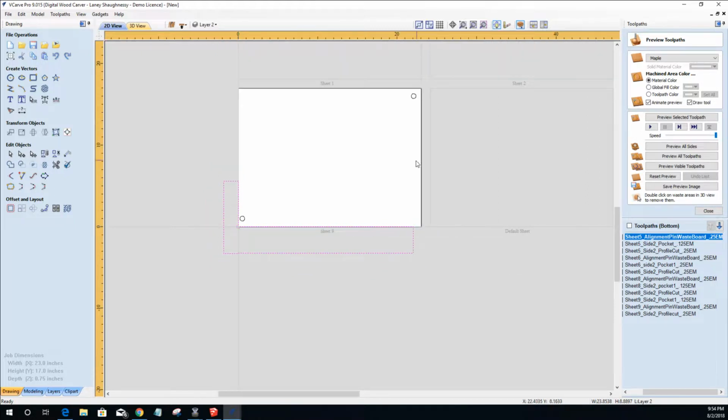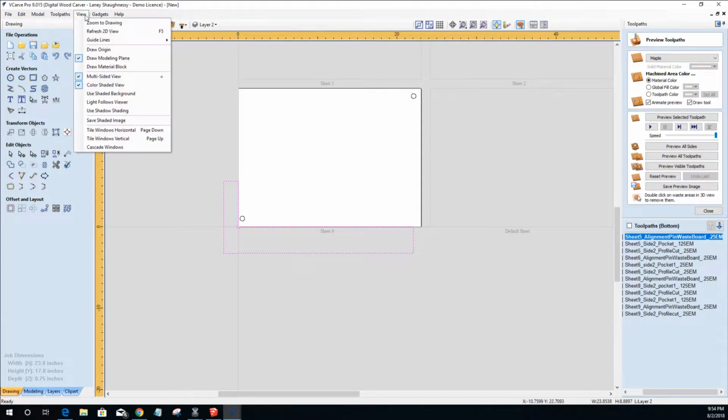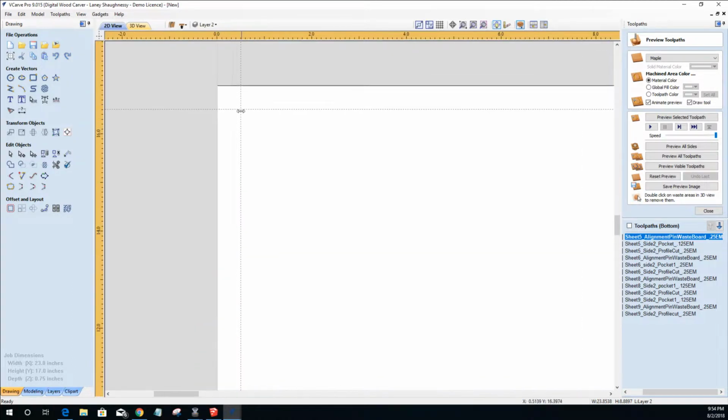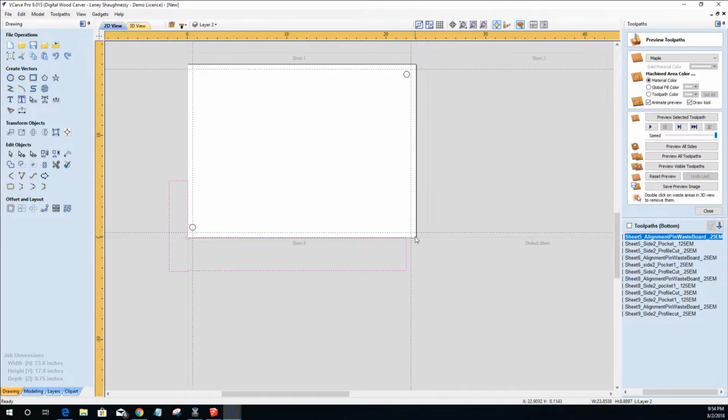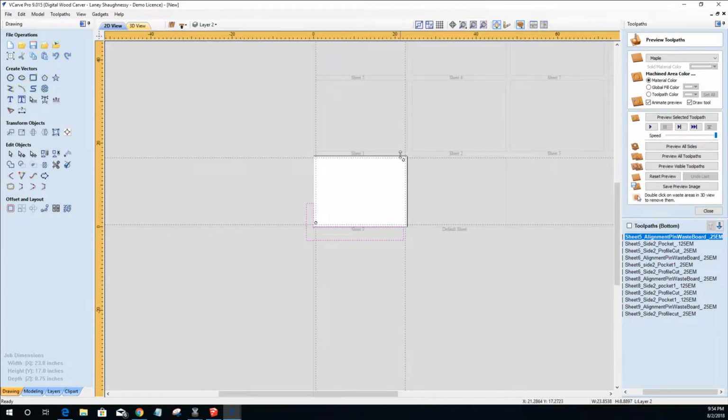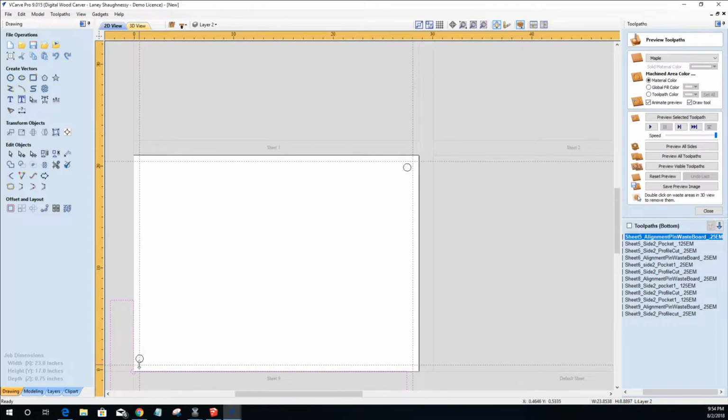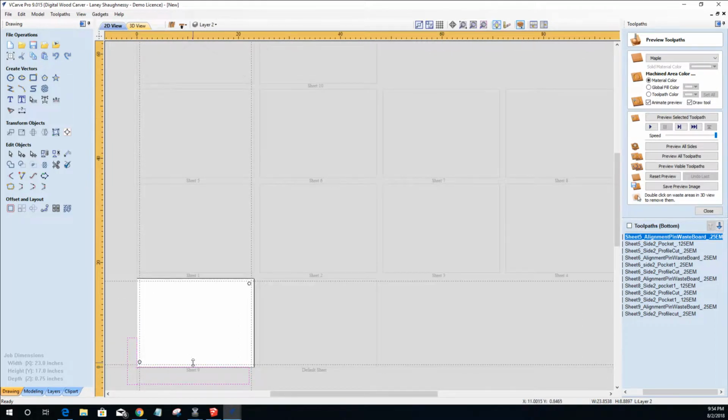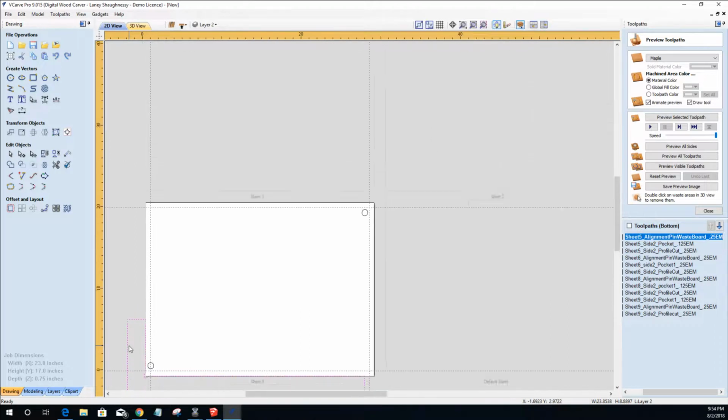Then when I carve my holes from side 2 onto the waste board, those alignment pin holes will line up for every single sheet that I did, because when I created my alignment pin holes, I created them using guides at specific measured points, a ½ inch in from this corner, a ½ inch in from this corner, which means I'm going to get a hole a ½ inch up here and a ½ inch down here, that when I flip this board over, it will fit right in every single time for every single sheet.